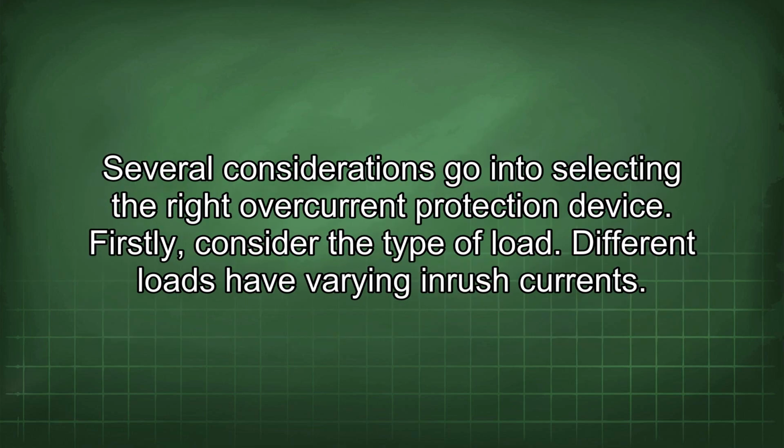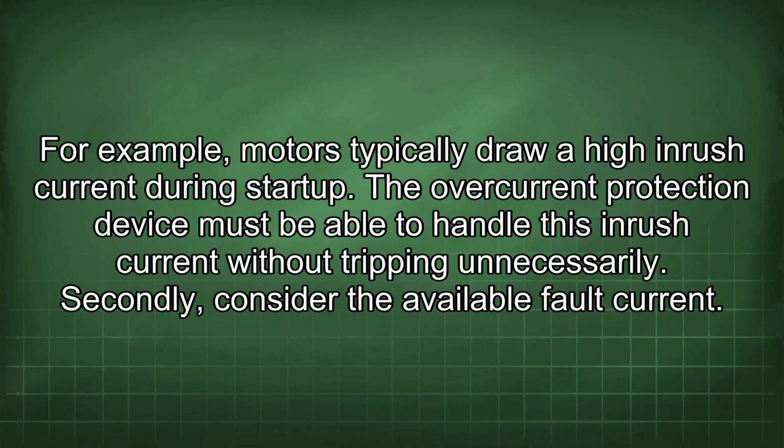Several considerations go into selecting the right overcurrent protection device. Firstly, consider the type of load. Different loads have varying inrush currents. For example, motors typically draw a high inrush current during startup. The overcurrent protection device must be able to handle this inrush current without tripping unnecessarily.